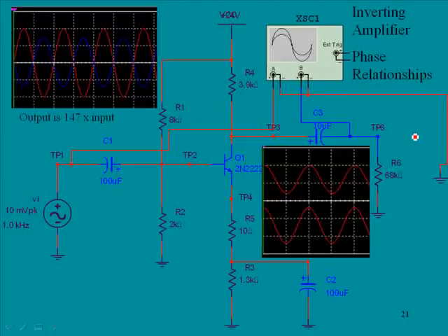And this is the amplifier that we had looked at a couple lessons back. Note here, the red line is on the input, going over to the O-scope, and then the blue lead from the O-scope is going down to the output, and this is the O-scope representation of those two positions on the schematic, and you'll notice that they are 180 degrees out of phase.